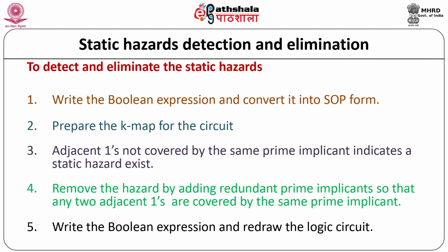Hazards are unwanted switching transients that may appear at the output of a logic circuit because different paths exhibit different propagation delays. The seriousness of hazards depends on the devices or the systems which receive the momentary transient signals. In case of digital system, the presence of hazards can cause the system to malfunction. Hazards can occur in combinational circuit as a result of changes in the delays. It also appears in sequential circuits as well.